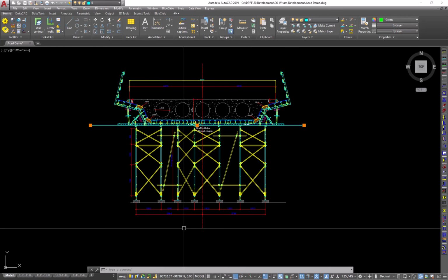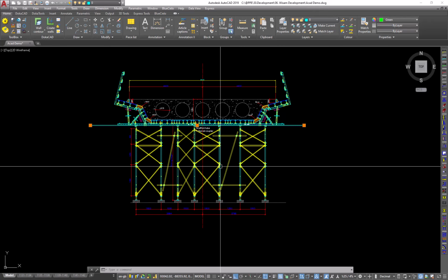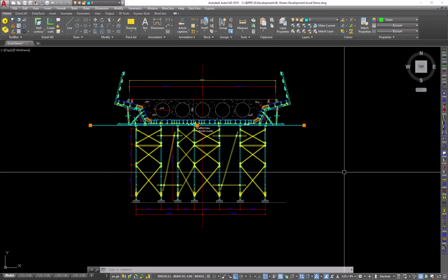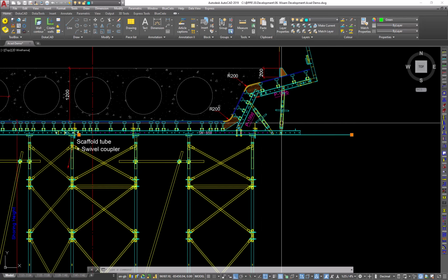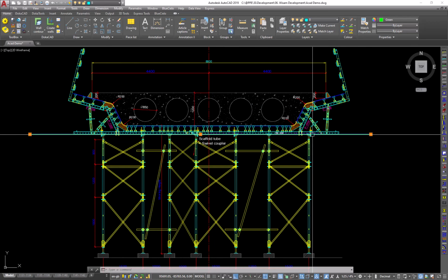This is our typical solution in AutoCAD, and in order to create it in Revit we need two things. We need the center line of the bridge around which we're going to align our helper families, which will be later converted to 3D towers. And the second thing is we need a surface from which we can obtain the coordinates for the towers.